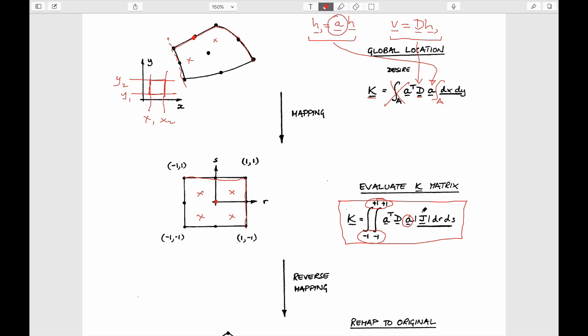And so that's one part of it. And the other part is that they have this interesting component here, which is a determinant of a Jacobian. A Jacobian is just a fancy name for a matrix of partial derivatives. And it's just a way of being able to map geometries from one scale to the other, which we'll see as well. So in other words, if you have a component here which has a side length on it, which is dx by dy, then you'd expect this to exist here.